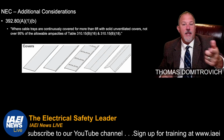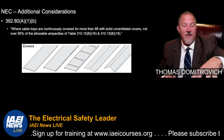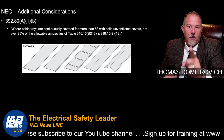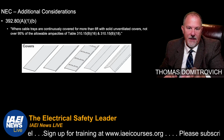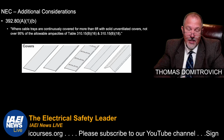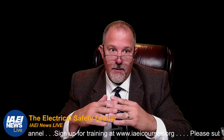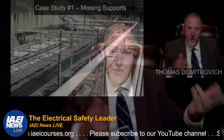So now, and we said this before, solid, unventilated covers and how they're installed. They have to be identified for use with that cable tray. Where cable trays are continuously covered for more than 6 foot with solid, unventilated covers, conductors are not over 95% of the allowable capacities of Table 310.15. So here's the thing. Remember, conditions of installation. When you put covers over the top of the cable trays, you're causing the retention of heat, and that's ungood. So you have to account for that in the ampacity calculations of your conductors.